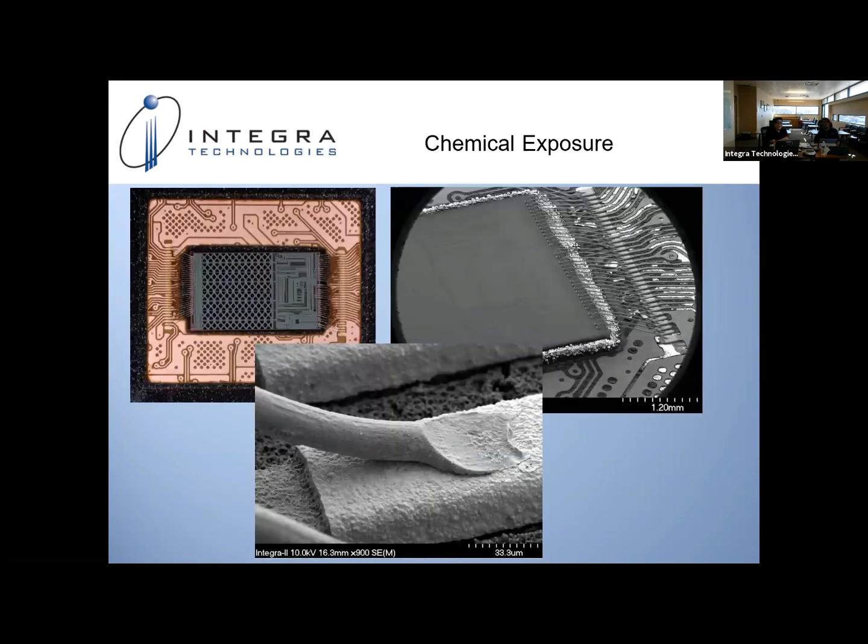And one thing to note there is MIL Standard 1580 Revision C, now that they're including coppers into requirement 16.5 for plastic, they do require, when you're doing decap, to fully expose the full length of the copper bond wire, which is different than golds, because in golds we're exposing 75% of the wire. For copper bonds, we will expose the entire length all the way to the stitch. So that is, again, why rinsing is so key.